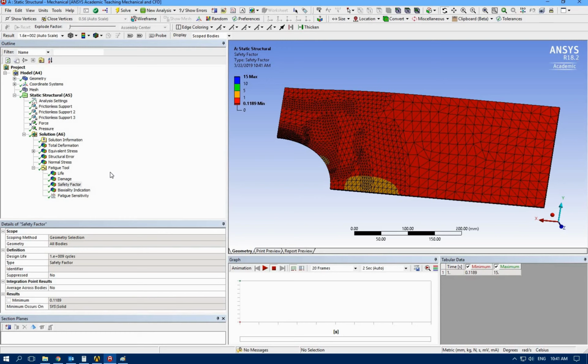If you have a cycling loading and your design is outside and it deals with environment, temperature, wind, different levels of surface, different types of loading, you need to consider correction factors, because correction factors directly affect the endurance limit, and they decrease that endurance limit.